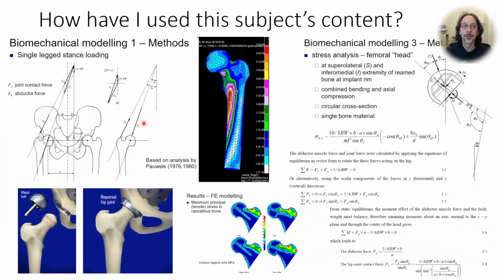I've also done something completely different in terms of context. This is looking at biomechanics and hip implants, so looking at prostheses and bone implants. Again, you can see making use of the fundamental engineering mechanics in order to understand what's going on in terms of the forces and loads that are being generated throughout the structural components. And then calculating stresses, looking at the internal actions, so internal bending moments, internal normal forces, shear forces, and so on. These are all things that you're going to hear about throughout this subject.